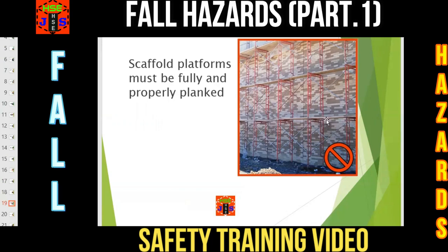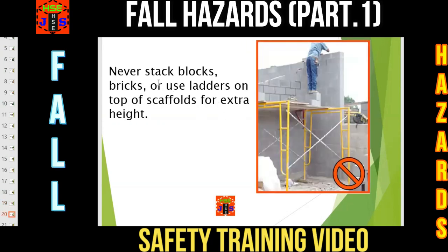In this case, it is not fully planked. They are keeping only 1 or 2 planks, and that is not safe. Never stack blocks, bricks, or use ladders on top of scaffolds for extra height. In this case, have a look. This gentleman is using blocks as a platform. This is an unsafe work practice, and this kind of work practice leads to potential workplace accidents.